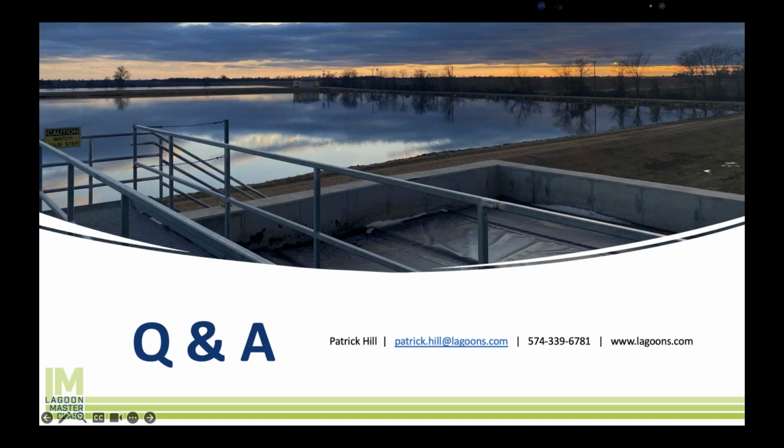Duckweed, if you add it, needs to be harvested, correct? If so, should it be in the last pond or the first pond of a system? So, last pond. That can be a nice natural cover versus the bird balls approach or the hexagon approach, and I've seen that. The downside to it is that wind will blow duckweed around, right? So it doesn't always universally cover the basin like you might want.